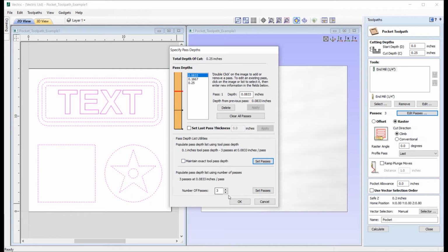So at the bottom here we could look at using the arrow key, and you can see that I can go up and down, so I can put in as many passes as I'd like, and with each arrow click you can see that the pass steps are updating up here along with the actual graphic as well. We can use the down arrow to decrease them. We can also type in a value, so we could put 8 and then use the Set Passes option, and then we can again just use the arrow key, so we'll just put that down to 4 passes there.